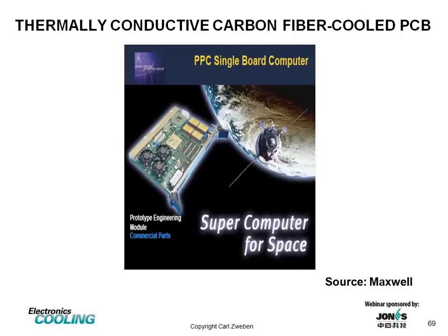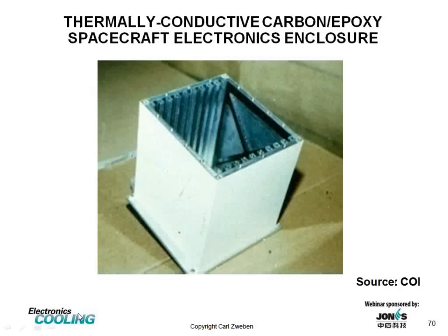So that approach of a constrained printed circuit board material is being used in a spacecraft supercomputer, single board computer. And in addition, if you use thermally conductive carbon fibers in the constraining layer, it also is a heat path.